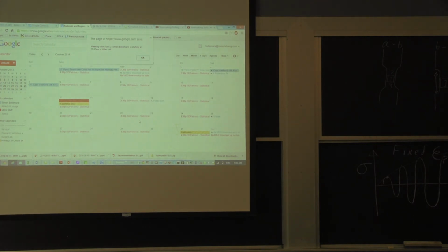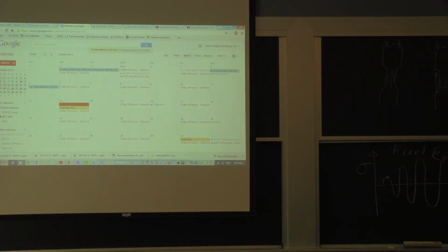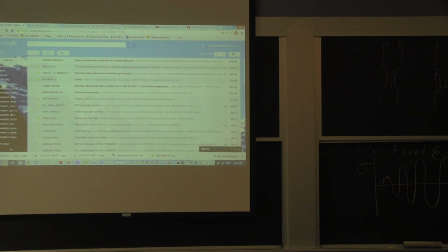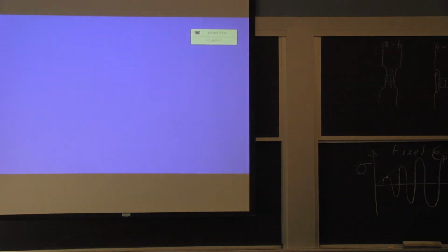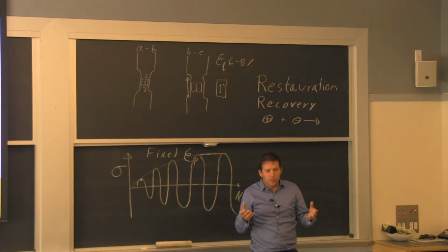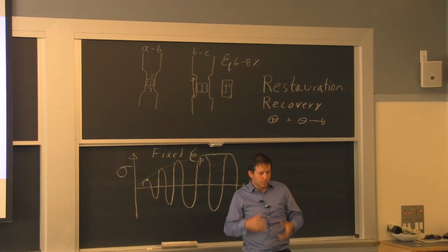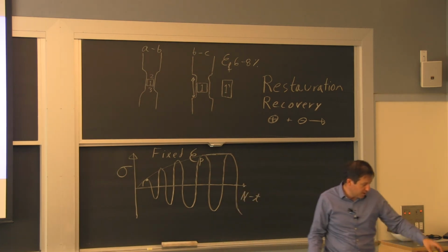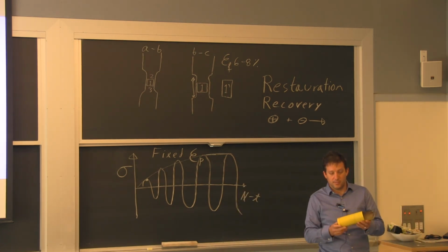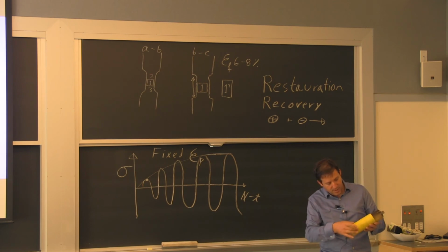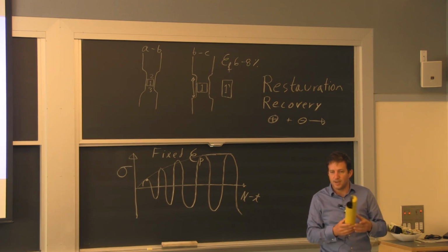So the main idea is we make a lot of use of the recrystallization, the grain movement, the effect of plasticity. The main objective being you need to homogenize the microstructure, and you also want to get to the shape you want. You typically don't want a billet. You want one of these sophisticated shapes. Maybe you want that canister for propane. This piece is actually from the bottom all the way up. It's a little bit like a soda can. It's made out of steel.